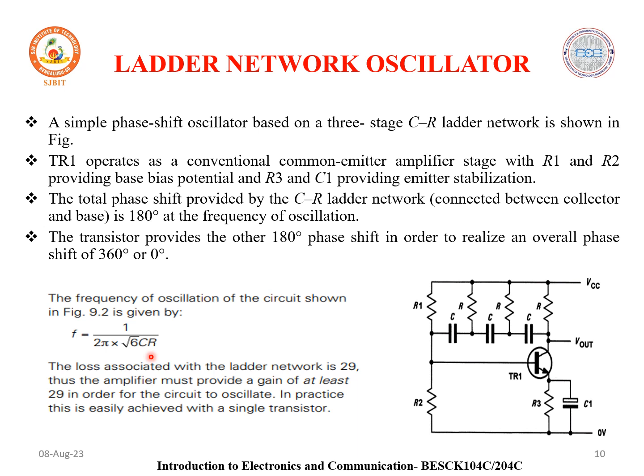The disadvantage of this ladder network is that the frequency stability is poor, due to the effect of temperature and component aging. When you use the resistor and the capacitor, the temperature will affect the component.